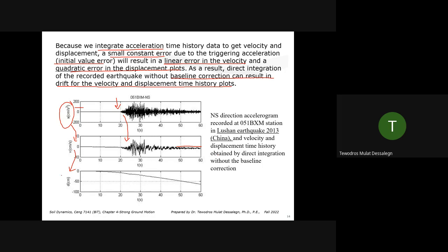And if you plot the displacement, it's even worse. It's like one-sided, like a static displacement. Normally, during a seismic vibration, the displacement should also oscillate around the 0 line. We shouldn't have it constantly on one side. This is because of error.